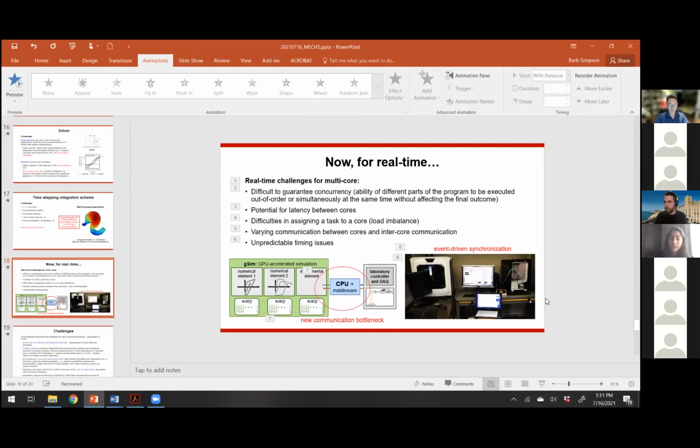About 20 milliseconds. Well, now you're making me do math, and it's a Friday. No, but yeah, it's 10 over 2048 is what we were using. I know that. And the issue is we did try, because we wanted to make it a little bit better, we did try 20 over 2048, and it wasn't accurate. We didn't get the degree of accuracy that we wanted. So the time step was too big for the integration scheme.